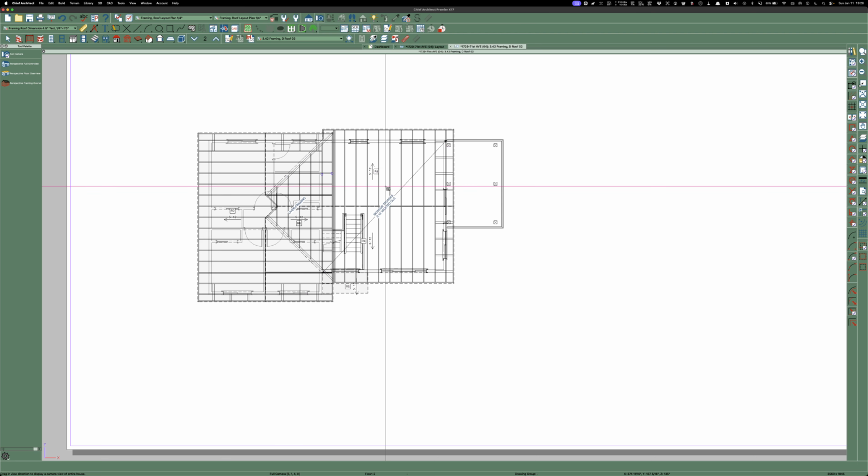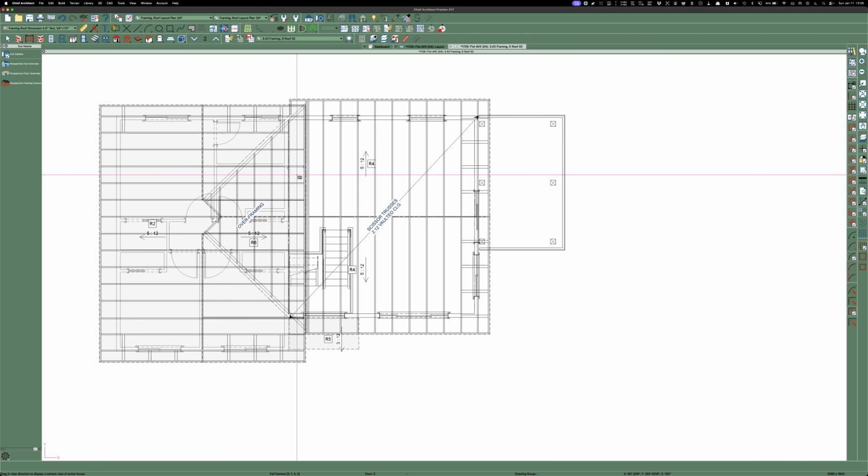People say build green, and they try to do it with the minimum amount of stuff. Well, trees grow back, and my idea of green is build it once, and you don't ever have to build it again. Not build it once, and then you've got a heavy snow load, and after a couple years you've got these sagging troughs. If you're going to use trusses, use thicker plywood. Don't use 7/16. Go 5/8, or I've even seen some guys, I love their attitude, use 3/4 inch subfloor on the roof. So there you go.